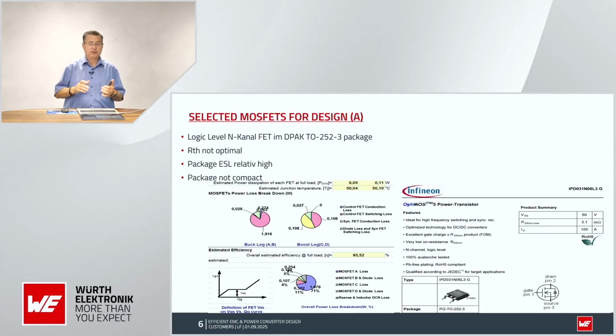Efficiency estimated by calculation is 95.5%, which should be quite okay. The package is not the best one, because it has quite high thermal resistance and also a not optimal resistance, quite high ESL, but okay, the price is good. The components will fit my decision.